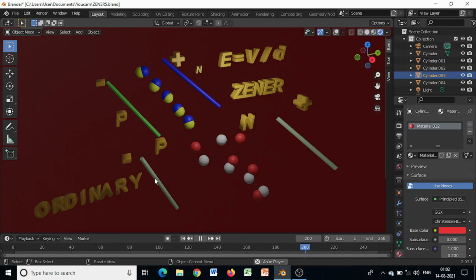So the reverse voltage applied at the diodes is the same in both cases, say VD. The concentration level in the Zener diode being high, to produce the same reverse potential VD across the depletion region, a smaller thickness is sufficient to provide the same number of electron and hole pairs.